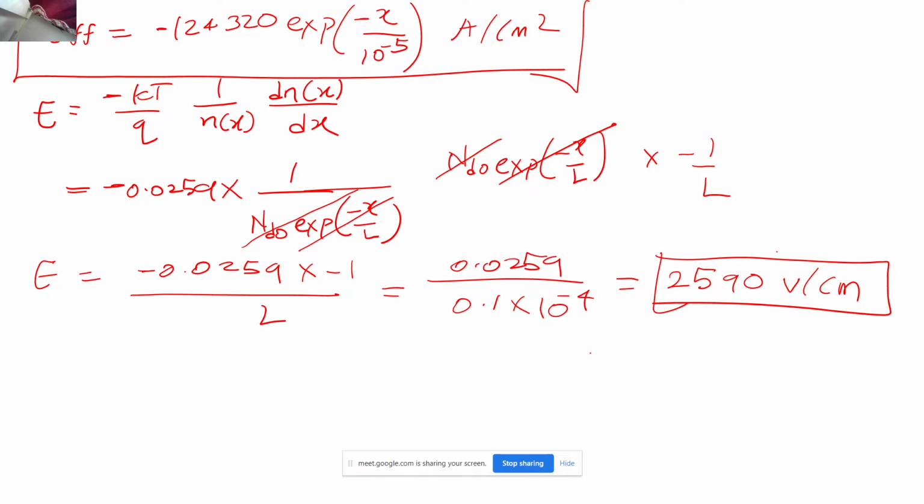So anybody, Gomati or Lakshmikant or Kushagra, any idea of when we will see electric field? What is the condition? If I take a simple piece of doped semiconductor, will there be an electric field? Yes, sir. There will be some electric field. Where? If I apply a bias, of course, electric field is going to be there across the material, right? But if I don't apply any bias, will we see it? No, you don't see that, right?